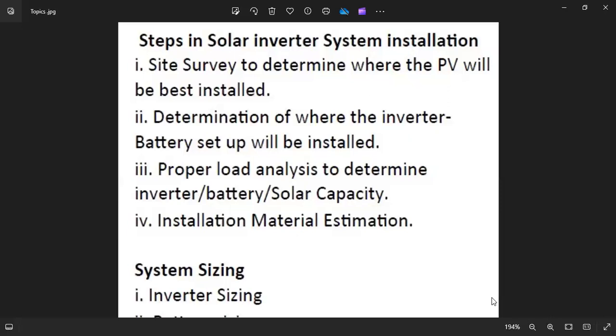Most of our inverters actually have chargers and inverters both in one system. So in one system, you have a charger, you have an inverter. When charging, it converts the AC current or AC voltage to DC current or voltage to store it up in the battery. So in the process of doing that, it's also a conversion process. Heat is generated, and in the process of pulling out the stored energy from the battery back to your power system or back to your load, it also generates heat. So it's a two-way transducer when it works as a charger.